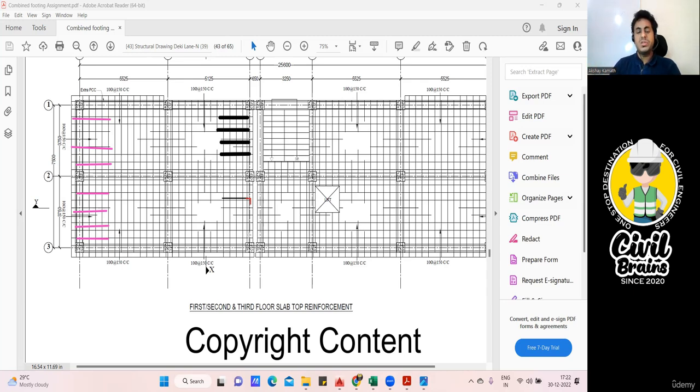So in this way, try to do this. Again, same thing. Number of bar will remain the same because you're going in the same direction, no? This is also 7,500 for this. When you're calculating for this, this is also 7,500. So number of bar remains same. Only the cutting length you check in the section, how much it will come.